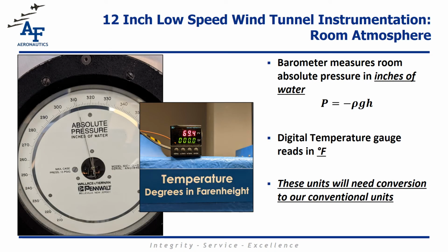We also have a barometer and digital thermometer to help measure the atmospheric conditions of the room. Take special note of the units used in the barometer. They are in inches of water, and the thermometer is in degrees Fahrenheit. Both of these will have to be converted for use in our equations.